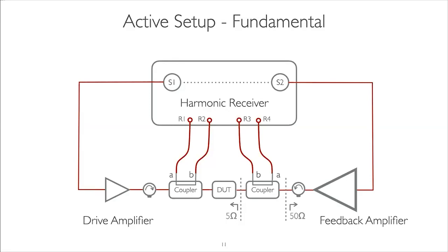Now, again, at low frequency, this is less of a problem because we have lots and lots of amplifiers available. But at higher frequency, this is a big challenge. Now I'm making these isolators blink because, as I mentioned earlier, the passive tuners are very broadband. You can have a tuner that goes from 800 megahertz to 26 gigahertz, 10 to 67. They're very broadband devices.